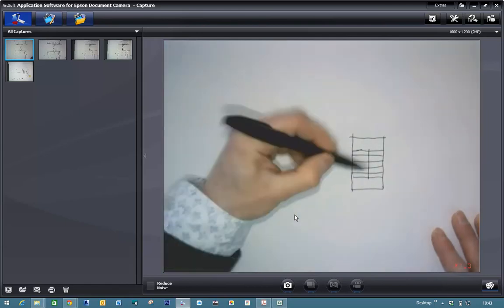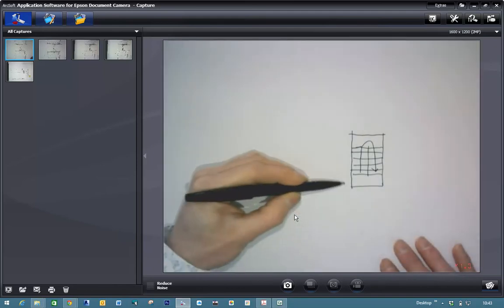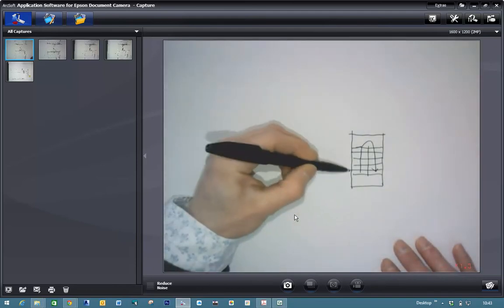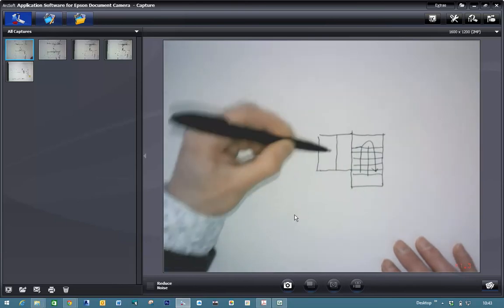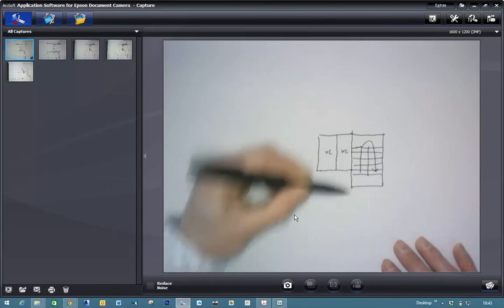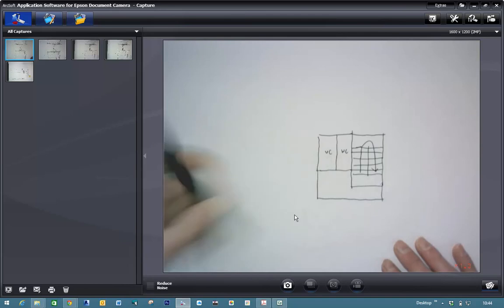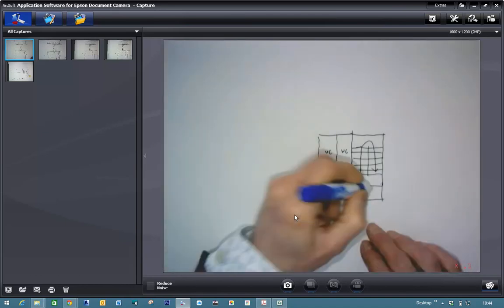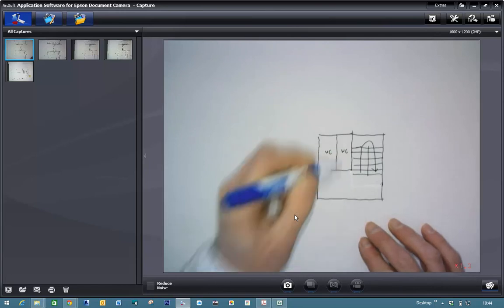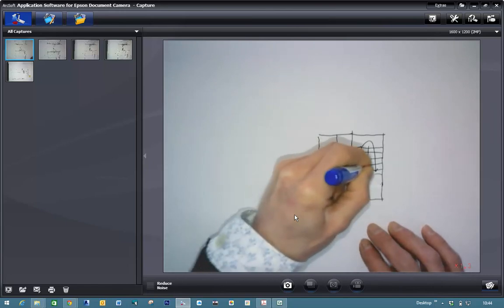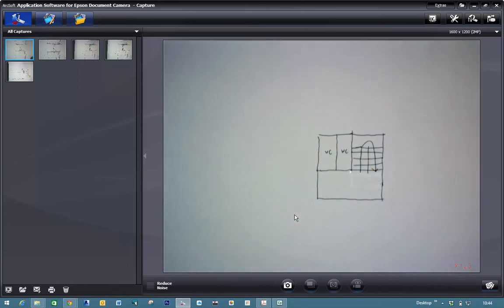So there's an escape stair. And what we're going to do here, let's put some toilets next to it. So there's WC. Let's make that a bit wider. Okay. You can have toilets opening onto an escape stair, because a toilet doesn't really present a fire load.